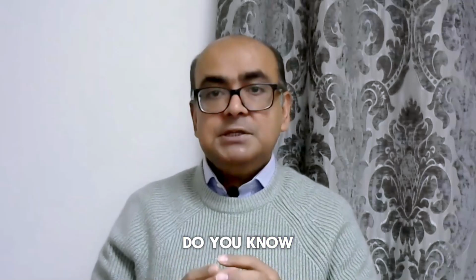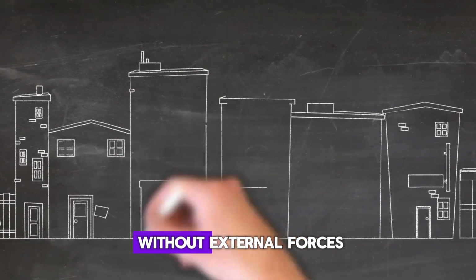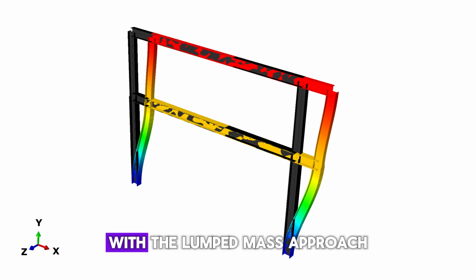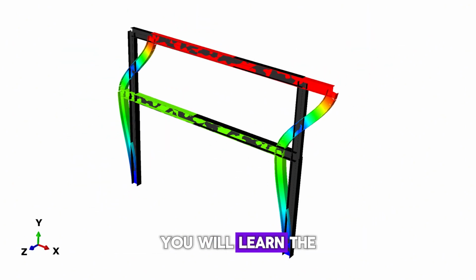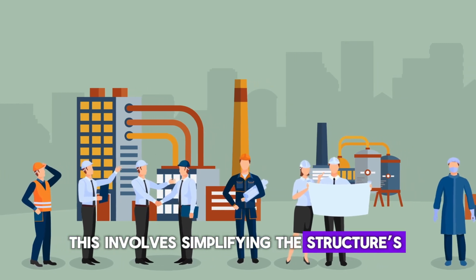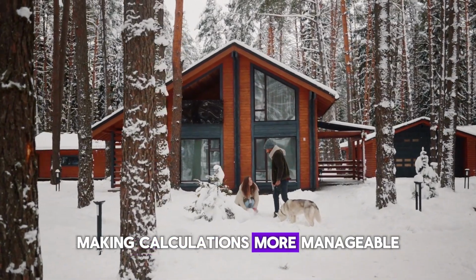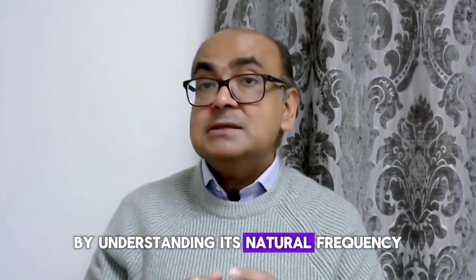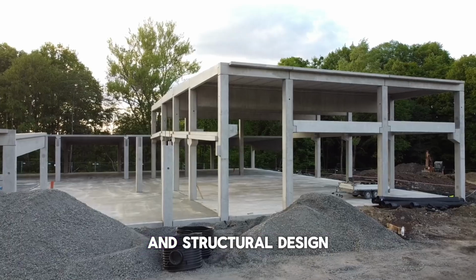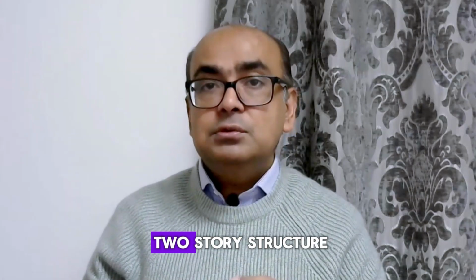Do you know free vibration of a two-story shear building is its natural oscillation without external forces? Using Abaqus and manual calculations with the lumped mass approach, you will learn the natural frequency of the structure. This involves simplifying the structure's mass distribution to key points, making calculations more manageable. By understanding its natural frequency, we gain insights crucial for seismic analysis and structural design, contributing to the overall stability and safety of the two-story structure.